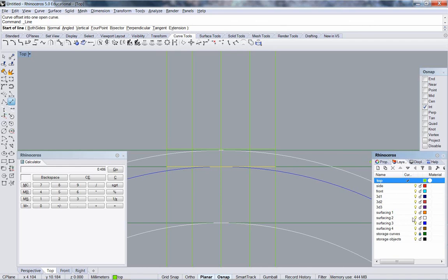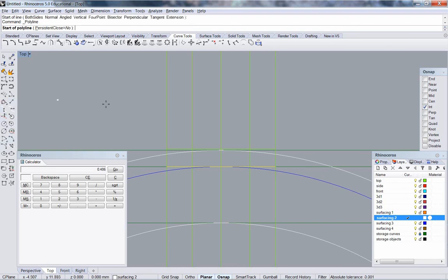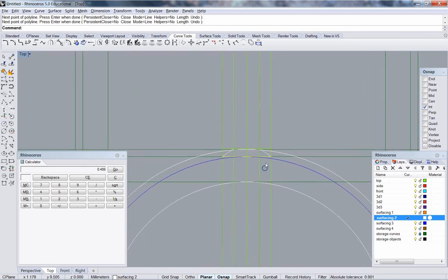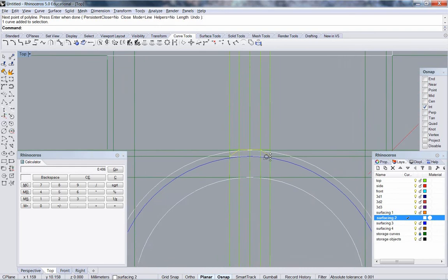So I will go ahead and draw. I can actually draw the whole crown. I can just draw the table, but why not use a polyline and draw a line from the edge of my girdle, top of my table, the other left side of my table, back to my girdle line, and hit enter when done. So now I have the crown of my stone.